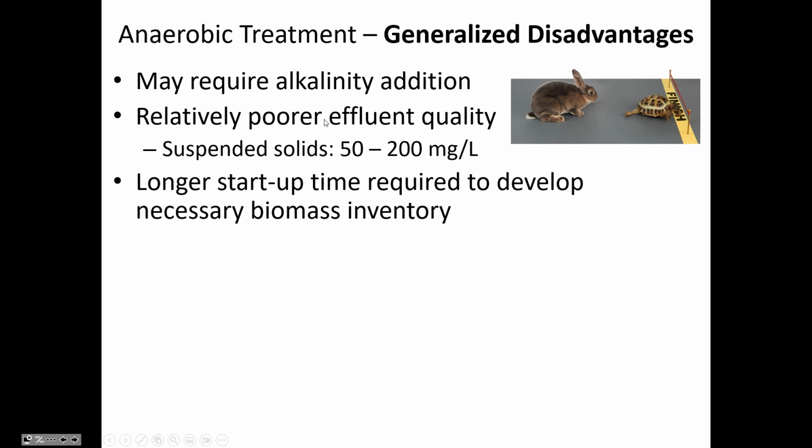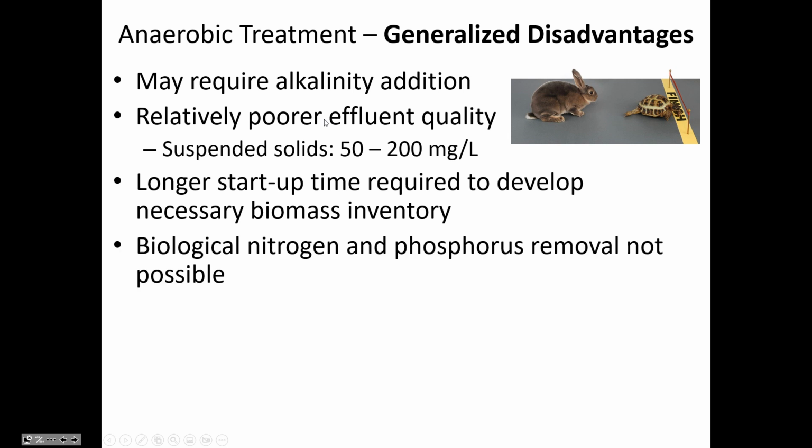And so it's just a long time that your process isn't working, and you're having to dispose of the sludge until you've got a good population of bacteria in there, and it's removing the BOD and generating the gas. And so that long startup time can have a lot of headaches associated with it, and expense as well.